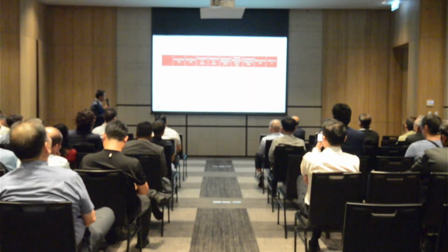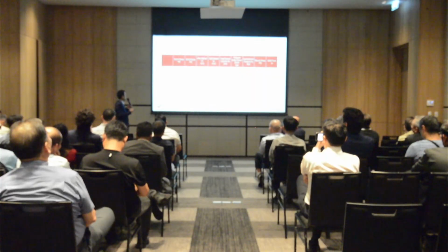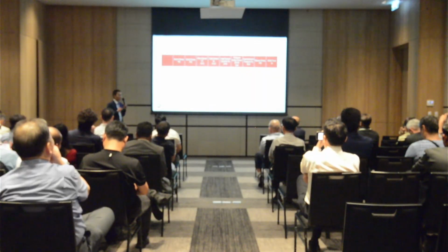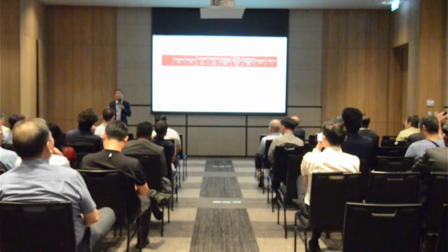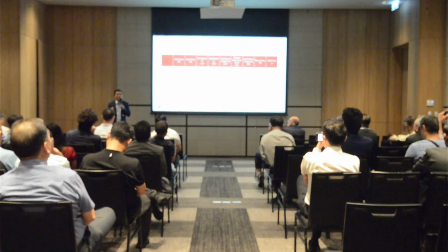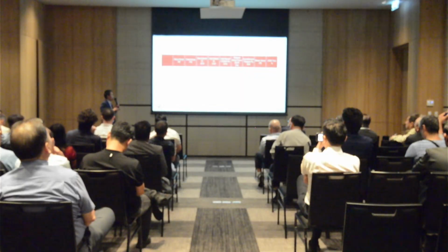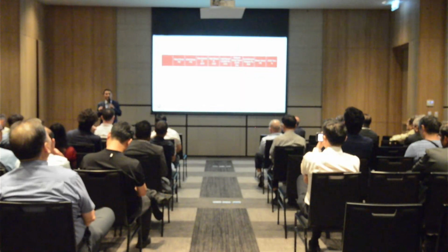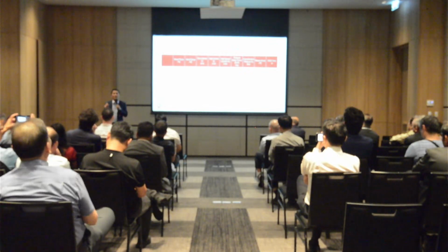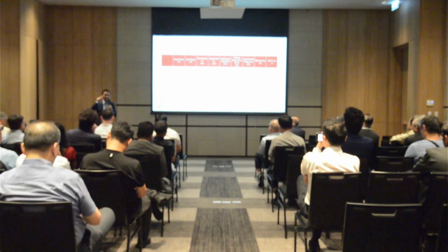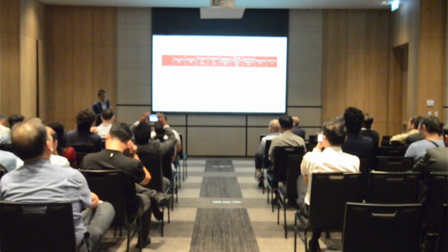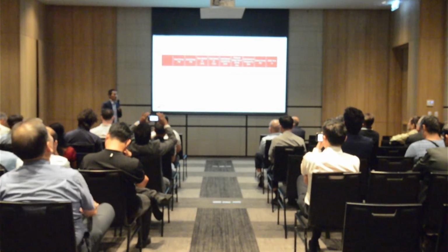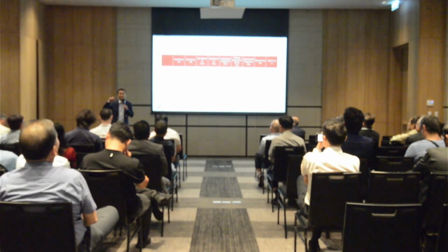In the end, in summary, GISS process is a viscosity control process. It's not the same as before. We only controlled the velocity. This process is a feeding compensation process. How to compensate? Hot die, a good mold, thick gate, to better feeding, to reduce pressure too. Also, if you don't want to change anything, it's still okay, but the benefit will be less.